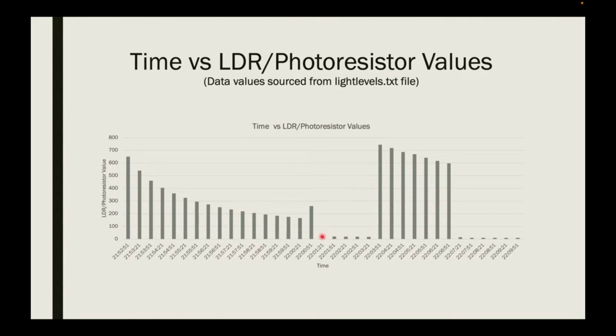In the second test case over here, this is with the room light on. We see a steep drop-off in the LDR readings, and at this point, the LED automatically switches off. In the third test case, I've attempted to block off all artificial and natural light, and we see a jump in the LDR value readings, and the LED is on. In the last test case over here, I've attempted to direct as much light as possible onto the sensor, and we see our lower values recorded.